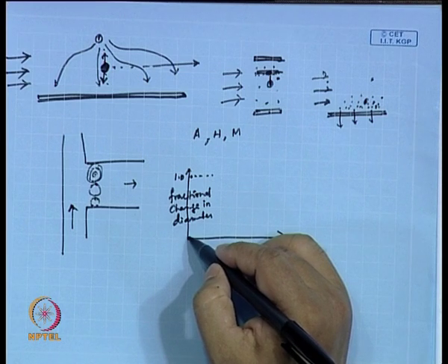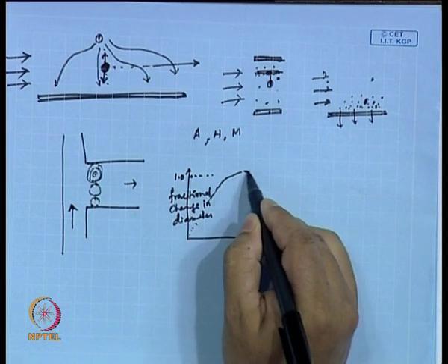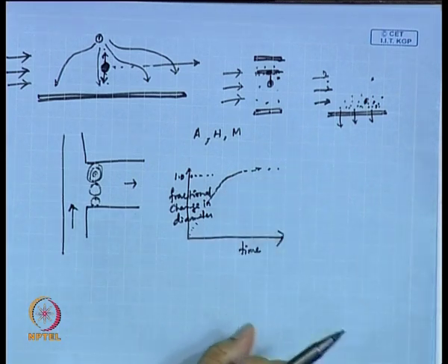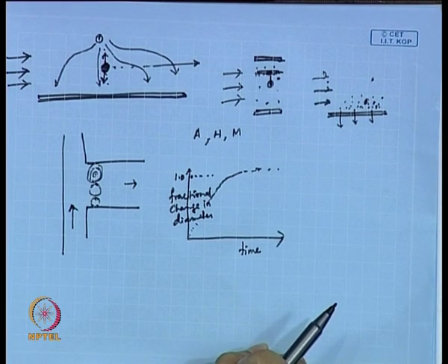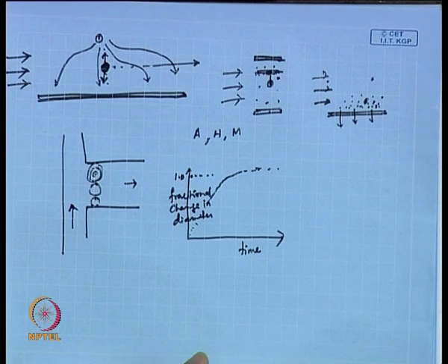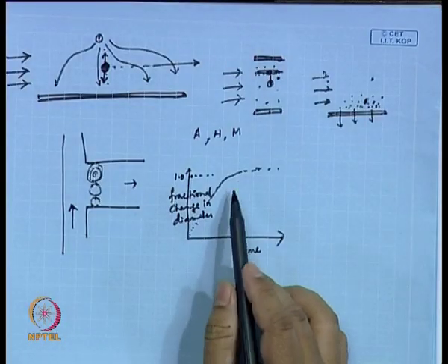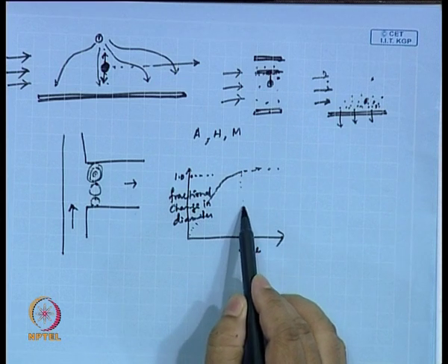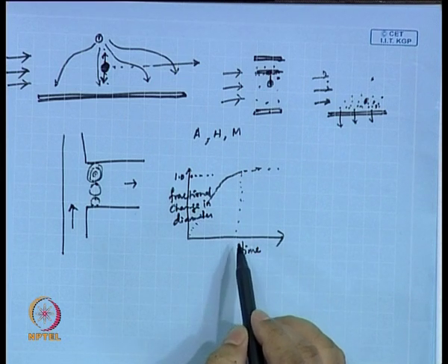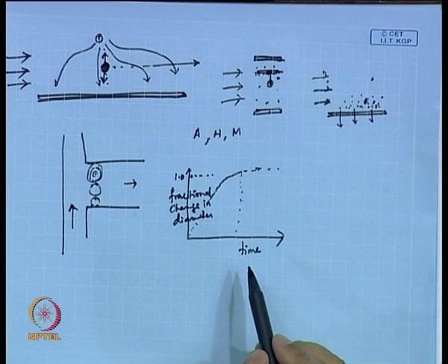So, with time you will find that the diameter will change. Suppose it was in a contracted state, and then suddenly you put the trigger. The moment you put the trigger, you start measuring what is the fractional change in diameter, and you would like to reach 1.0, because when you reach 1.0, that is the point when the valve would be completely closed. So, you should accomplish this within seconds, then you consider this response time to be good, right.